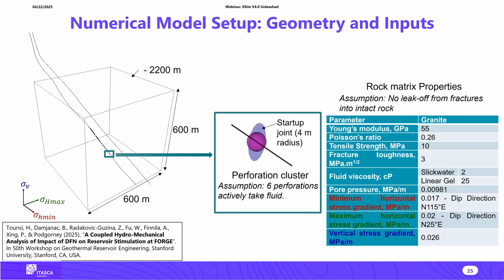I think there are also limitations on the type of frac fluid, i.e. incompressible only, and on the type of rock failure, i.e. brittle only. Is that correct? Yes. XSite assumes incompressible fluid. My apology, I didn't mention that. It assumes incompressible fluid, and the lattice and the bonded block model are good models for simulation of the deformation and damage of brittle rocks.